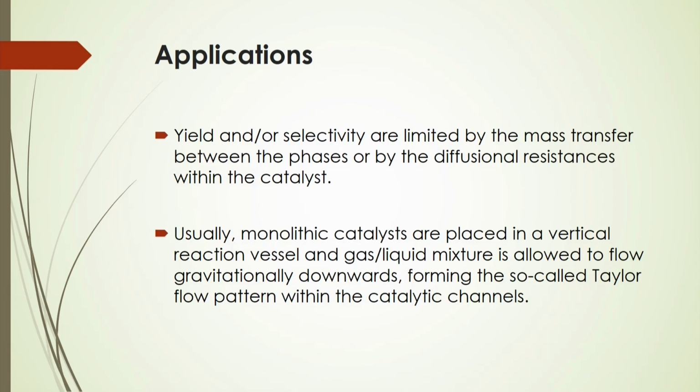And usually monolithic catalysts, as an example, are placed in a vertical reaction vessel, and the gas-liquid mixture is allowed to flow gravitationally downwards, forming the so-called Taylor flow pattern within the catalytic channel.